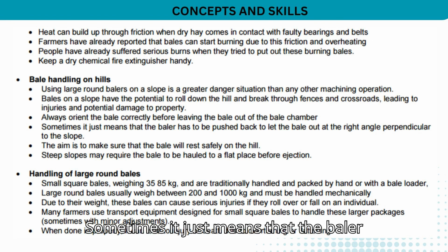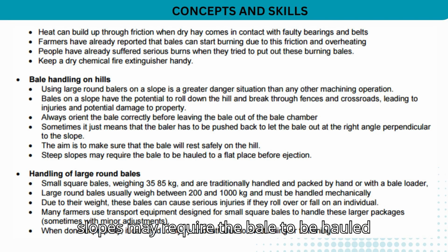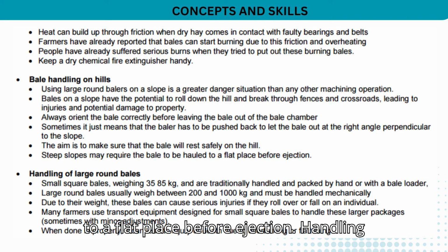Sometimes it just means that the baler has to be pushed back to let the bale out at the right angle, perpendicular to the slope. The aim is to make sure that the bale will rest safely on the hill. Steep slopes may require the bale to be hauled to a flat place before ejection.